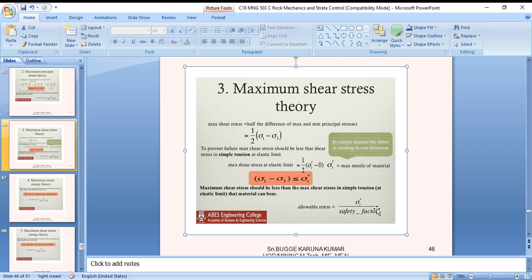However, the design specifications for any underground structure for a military or industrial purpose may be vastly different from those for a mine. In the former, the structure is designed for a high degree of safety over a long lifetime, whereas in a mine, because of economic pressures and a desire to conserve resources, there is a premium on extraction of as much ore as possible. The problem may become one of designing an opening that will remain open long enough to remove the ore.